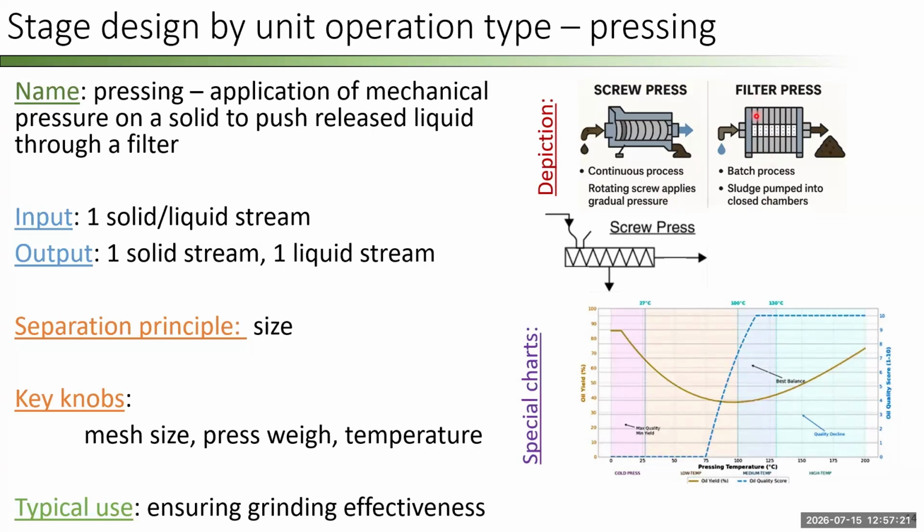In general, rather than having just one giant filter bag surrounding the material, we generally section that off into sub units with different bags, just so that the filter cake doesn't build up too thickly on that one edge. So think about this as a surface area to volume ratio. I have a thinner filter cake as I'm constructing this, so I get more of my liquid out for however hard I can push.